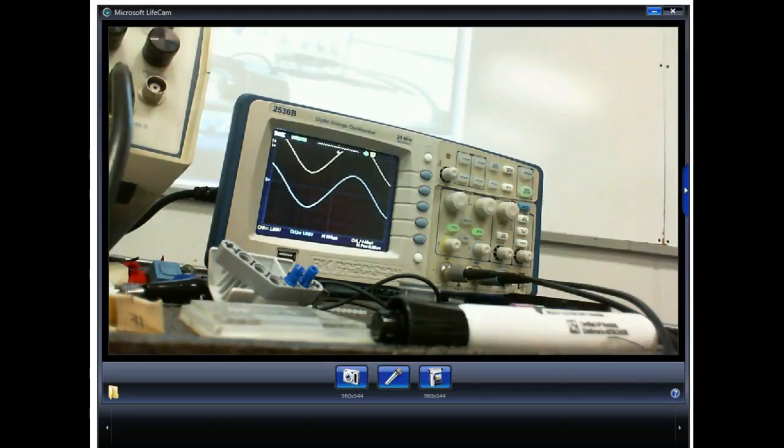Yeah, verify your power supply. Verify the problem, right? If the problem does exist, what are you going to do? Check power. So we would have got this fixed just like that. We expected it to measure 10 volts. It measures 5 volts. We would move into troubleshooting our wall, our power supply.